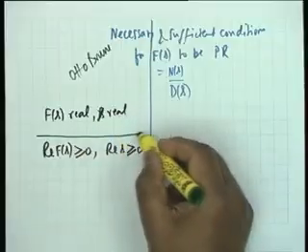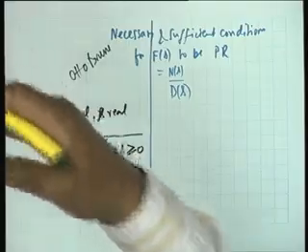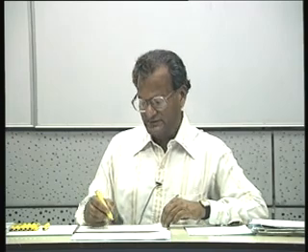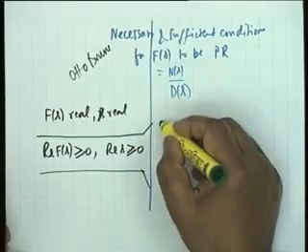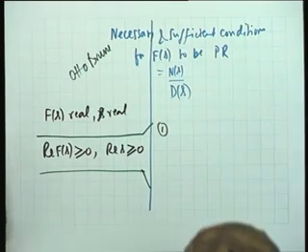All right. So, Brune said, well, it can be done in a simpler fashion. This condition, this is the difficult condition, because this is almost obvious. As soon as you look at the function, if there is a complex coefficient, you throw it out. Okay. Now, as far as this is concerned, he said, do three things. Number one, first find out if all poles are in the left half plane. That is, how do you find this?